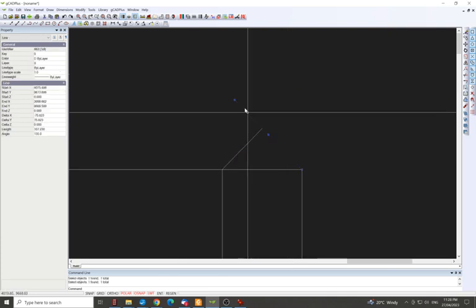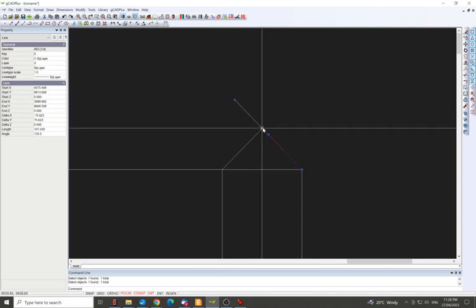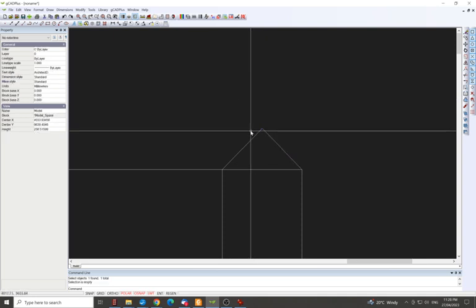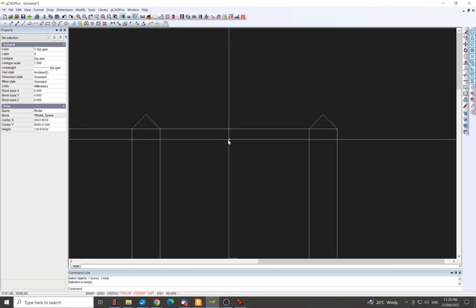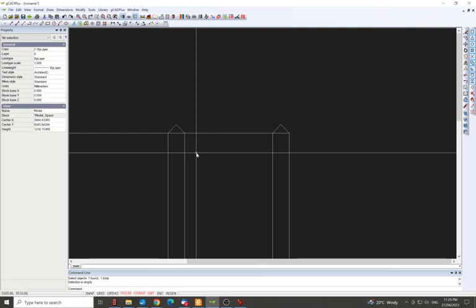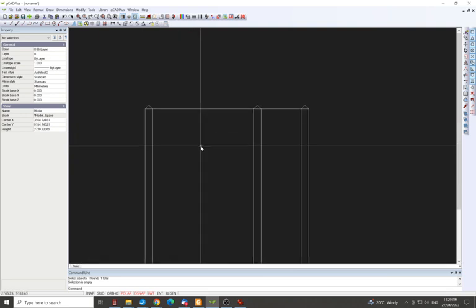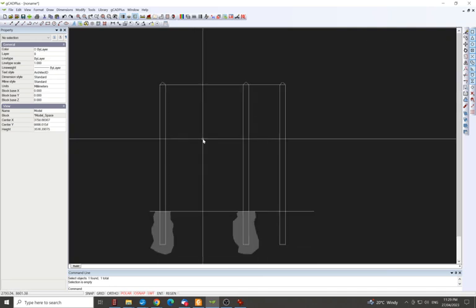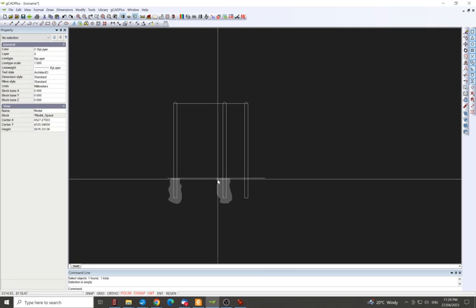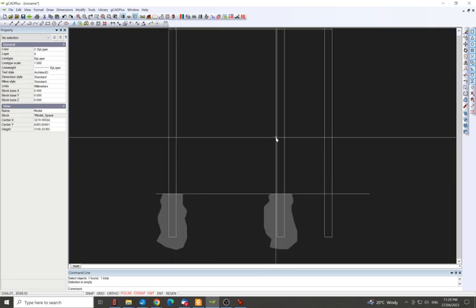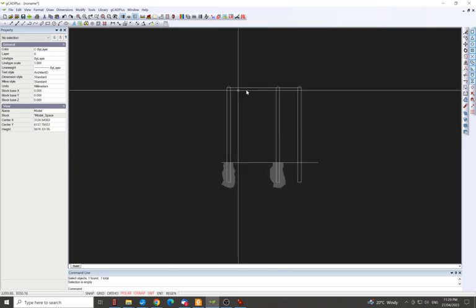We've got some rough idea of the height we want, typically 1800 tall, these gates. So we make the gate frame at 1700 and that gives a bit of play each way, and to put panels on there that are 1800, unless the gate is all manufactured. See, this one's going to have timber battens, so we're going to do the gate height with the battens, and we're just going to keep the frame a bit shorter. And because we're only getting the frame made by the gate manufacturer, we've already put the posts in. This is not so much about the posts, this is more just about the frame.